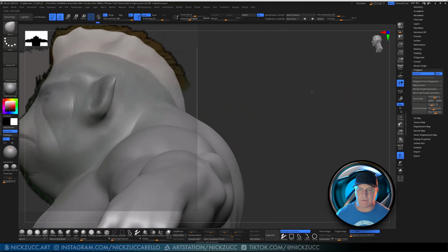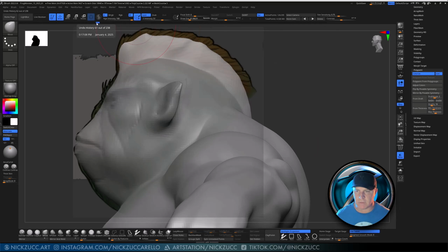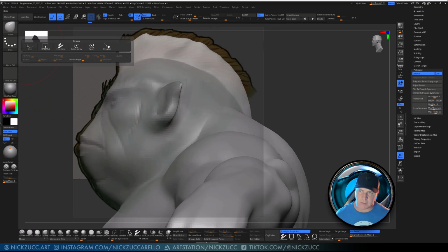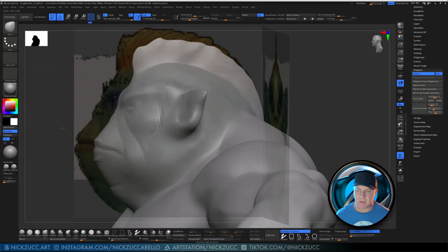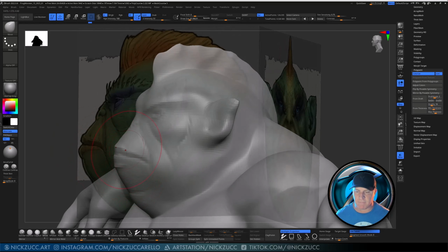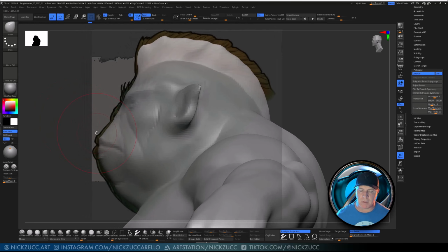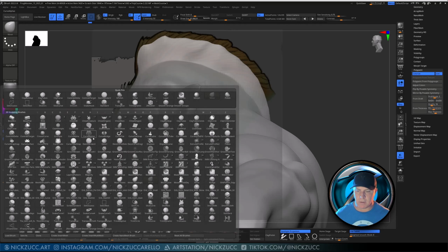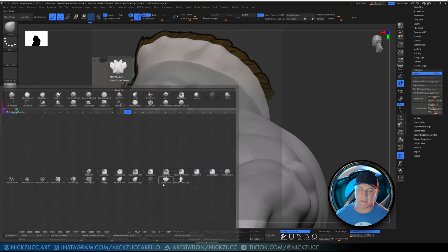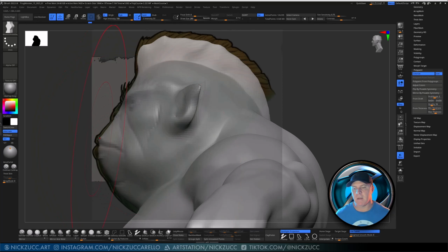If I move to the side view and take a look at what's going on with the side view, I know I did this as well for this. So we can use the move brush to move things around, and that'll be fine, but it's only going to grab a local area, like maybe some falloff right in here. There is another move brush type that we can use, and it'll basically take the entire model and shift it over. So if we tap B and then go M for our brushes, there is this move infinite depth. And if we do that and we click and drag, it drags everything forward and it keeps the falloff of the brush and it keeps everything consistent going across the model.